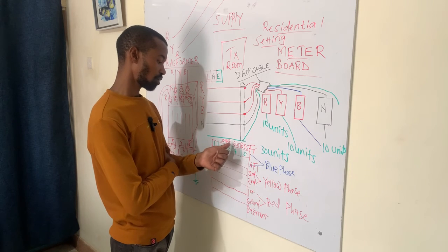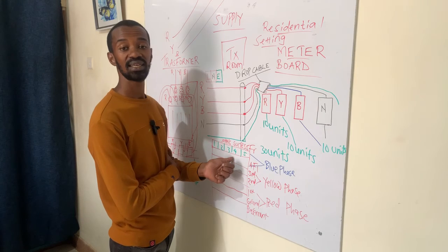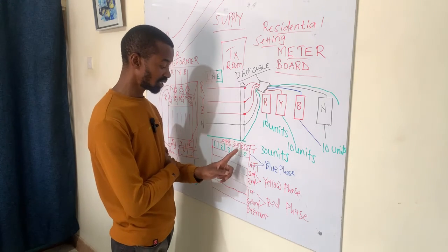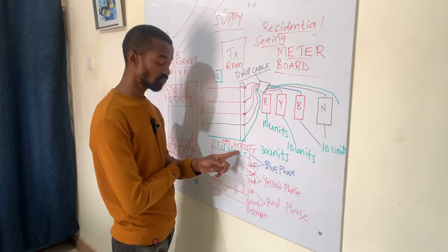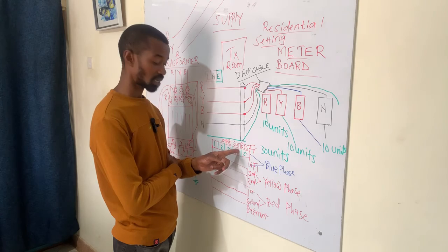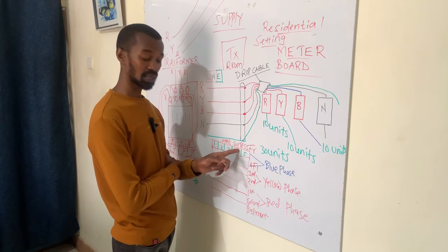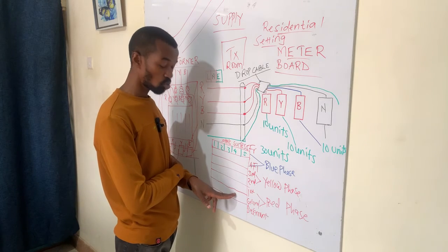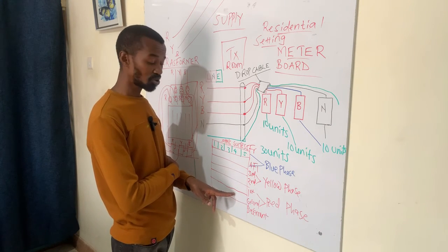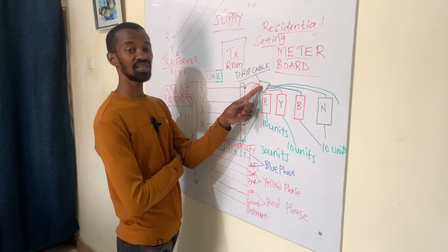All of these residents are at home and they have connected their appliances to the electricity. You cannot dictate to a customer who is on the fifth floor, at house number 5, that they should not put on their microwave because there is someone who is using their washing machine on the ground floor, because it will overload the phases, or it will strain the cable.